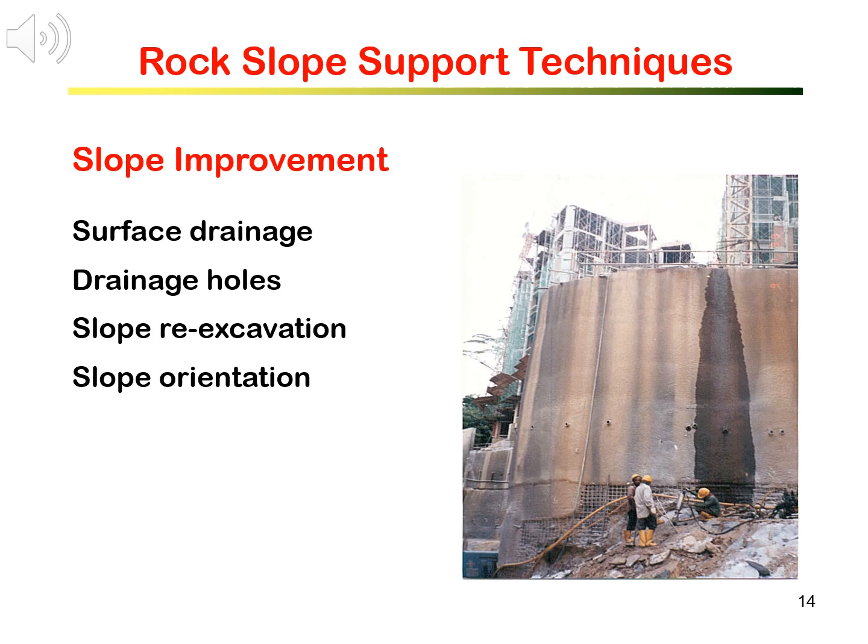Drainage is part of a slope improvement. You can see the drainage holes in the lower part of the slope covered by the shotcrete in the photo here. Drainage can also be provided at the surface to minimize the water seepage into the ground. On the whole, drainage is to reduce the water pressure in the slope that otherwise becomes an additional driving force pushing the slope to fail.